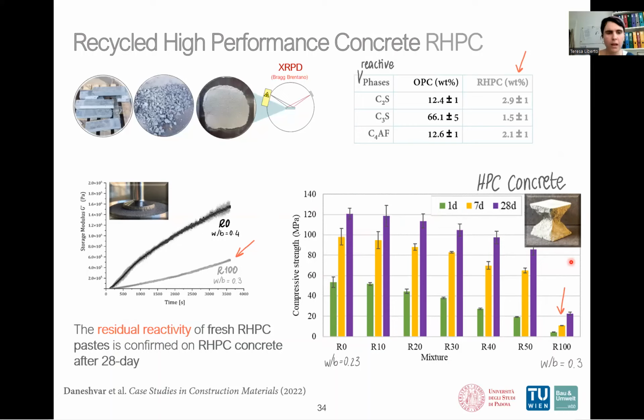Now, this is normal. But what we didn't expect was this residual reactivity of R100, so when only RHPC is used as a binder. In fact, we can reach 22 megapascal after 28 days, which is not bad at all. So we can say that the residual reactivity of fresh recycled HPC pastes is confirmed by the concrete after 28 days.